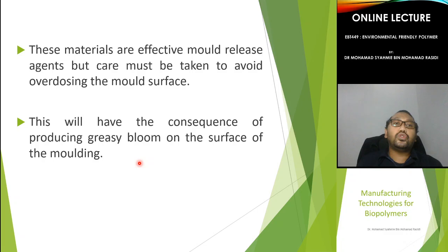So when you use a mold release agent, the main concern is that you cannot use more of the additive than you are supposed to. When you overuse the material, the consequence is that the product will have a greasy bloom on the surface of the molding.